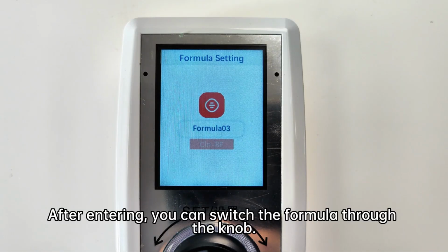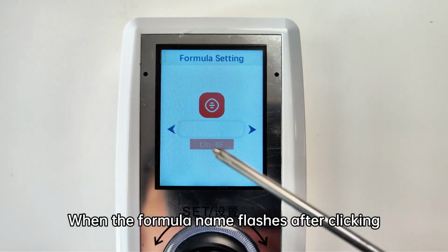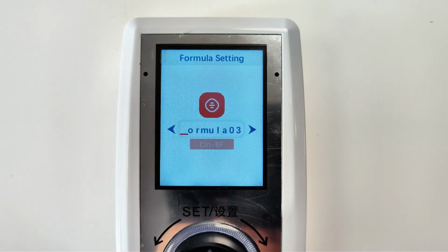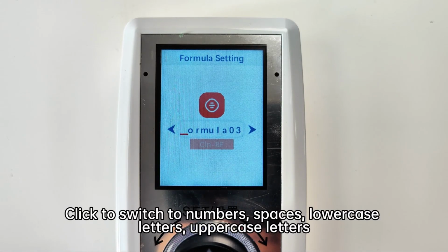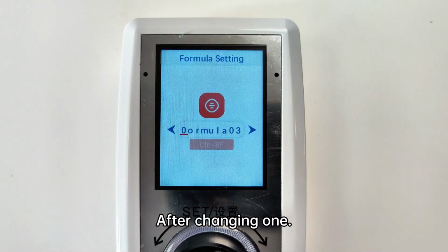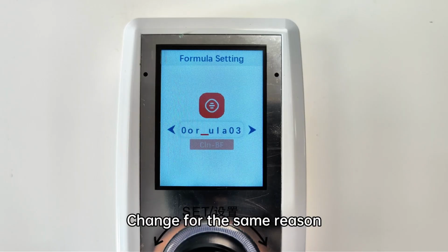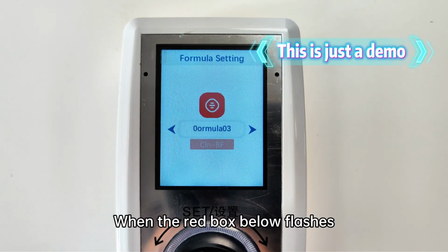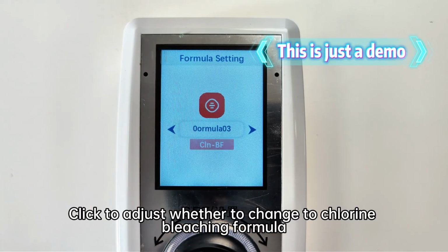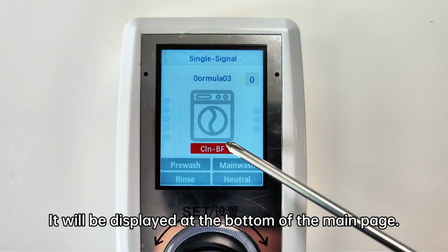After entering, you can switch the formula through the knob. Click after confirming the formula. When the formula name flashes after clicking, click again to change the formula name. Click to switch between numbers, spaces, lowercase letters, and uppercase letters. Make changes via knob. After changing one, long press to switch to the next one. When the red box below flashes, click to adjust whether to change to chlorine bleaching formula. After selection, it will be displayed at the bottom of the main page.